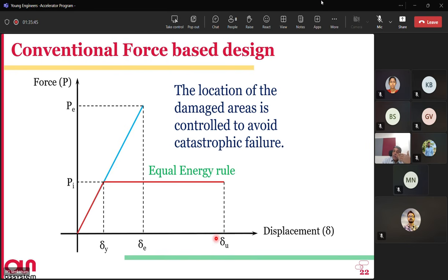But if you allow the displacement to be taken by elastomeric bearings, then you cannot allow another place where you want a plastic hinge to form. Therefore, all the rest of the structure must be in completely elastic zone. So you cannot reduce the response further than what you get out of introduction of elastomeric bearing.